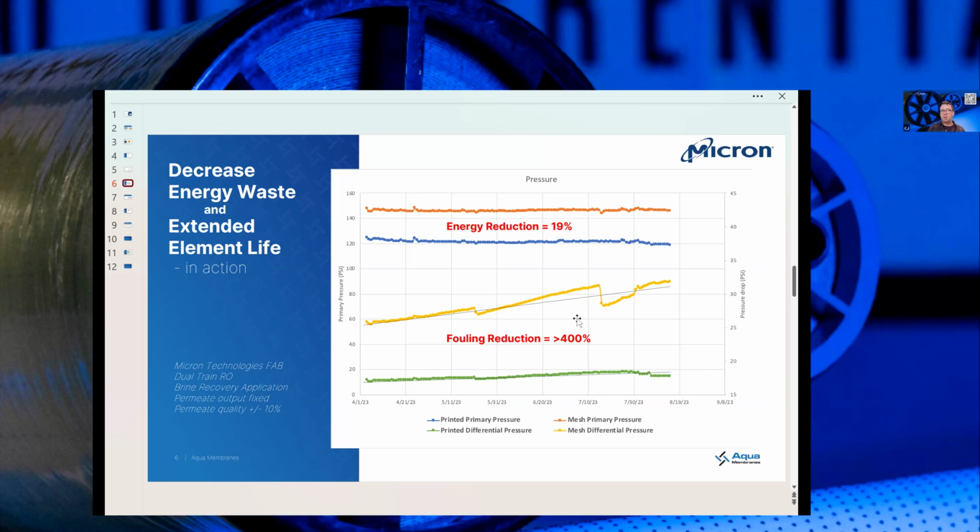That also corresponds with locations, though, where mixing is no longer balanced. There's thicker channels where most of the flow is going through, leaving less flow for other areas. And what we ended up seeing was actually faster rates of pressure drop increase after each of those pressure reductions that occurred.